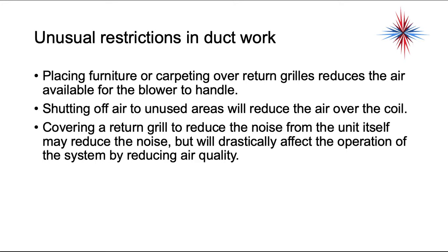The other thing that happens very frequently, especially with people who've retired or who have closed off part of their house because no one's living in it anymore, is they shut off the air to the unused areas. Well, this greatly reduces the air over the coil. I know one customer who shut off the air to 4 bedrooms that are no longer used since their kids moved out. So all of a sudden, we've basically cut the size of the house in half.